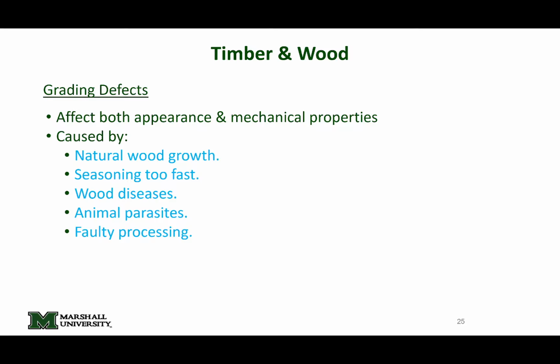For example, I don't know if you all can see this on this piece of wood. Does everybody see this part right here? There's a sort of separation along, or perpendicular to, the grain. Those are fibers in this element that are separated. If I take this and I bend it, it's not going to behave as well as if it was all uniform like it is down here.